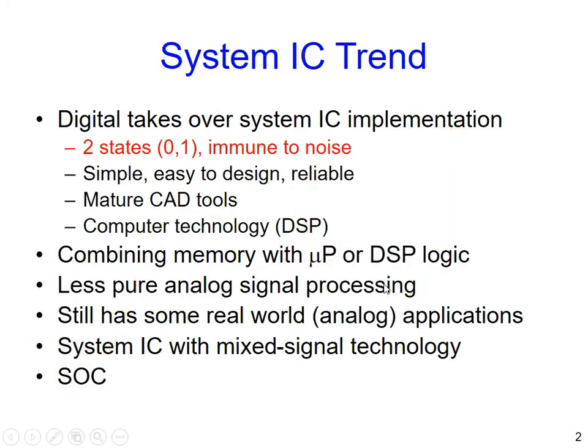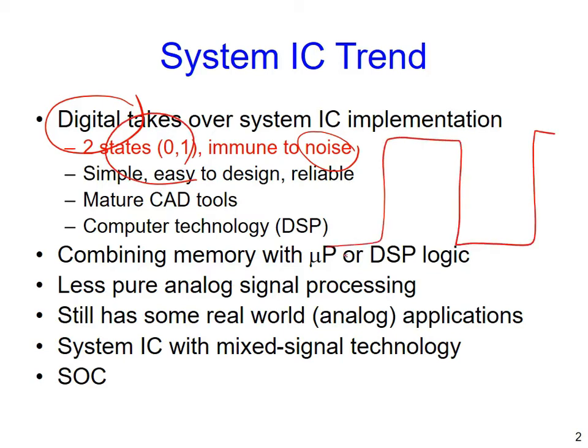Why would we like to do this? From the very beginning, we would like to focus on digital circuit first. Why? Because if possible, we would like to digitize almost everything. Why? Because digital signal is quite insensitive to noise. But why? They have only two states, just like this, only 0 and 1. During operation, it will be jammed by many kinds of noises and interference. So finally, you will see something like this, right? Is it harmful? Usually not.